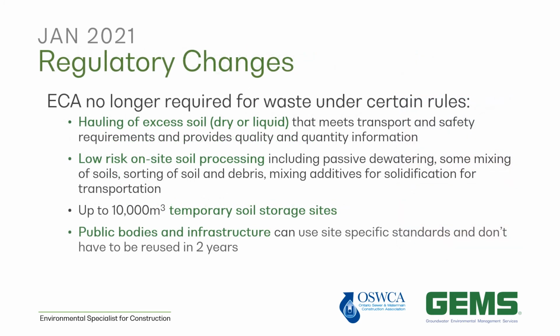The other new change that came out January 1st this year is that the requirement for ECAs has been removed for certain conditions. So if you're hauling excess soil, whether it be dry or liquid, and it meets the transport and safety requirements, you just need to make sure that you have your quality and quantity information available. That means the truck driver can be asked to provide that information.